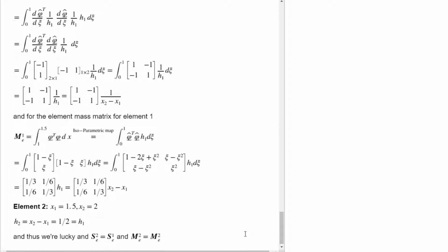So the strength of the finite element method really is that h can change. It can be any size, really. And in the finite difference method, that's usually not the case. You usually have the same range everywhere. And in 2D, you have a conformed mesh.